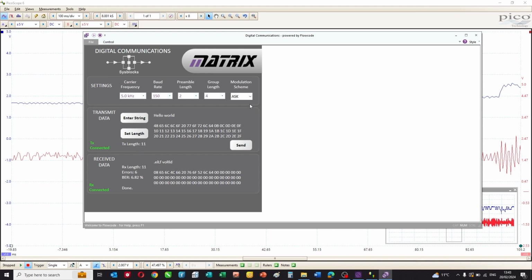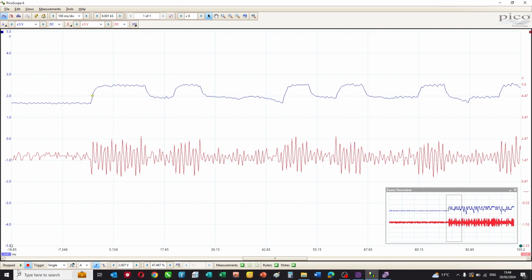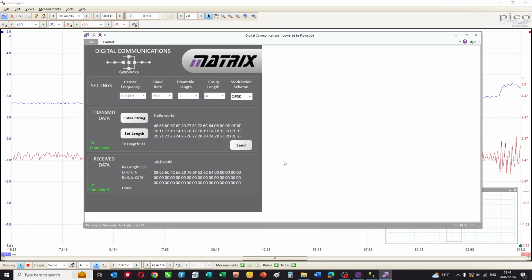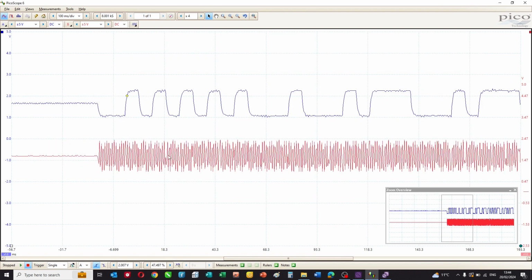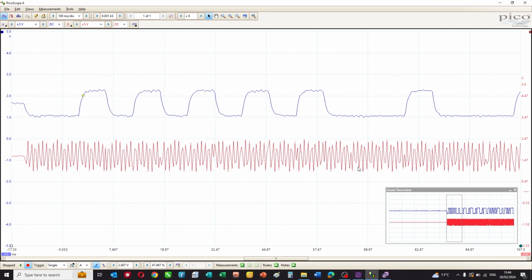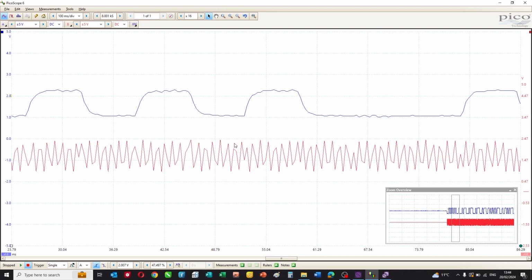And it gets really interesting when we start to move to the more complex phase shift keying systems. So in this case, let's just take a look at how QPSK is transmitted. So I put the noise back down to 0 dB, I set up a simple transmission of QPSK, and I trigger the scope again and send a byte. You can see that now, of course, it's very difficult to see the phase shifts in the transmitted signal, but you can just see phase shifts at certain times.